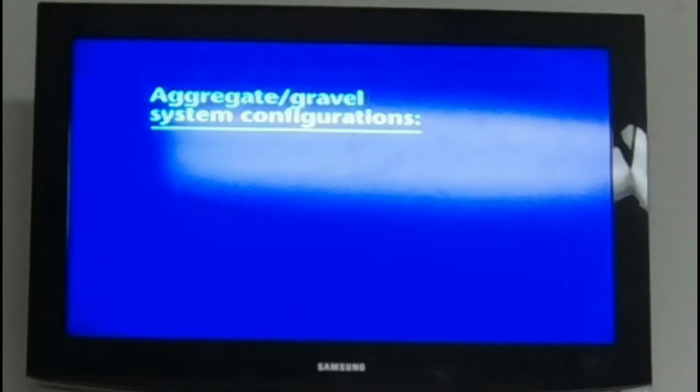On level or sloping topography of 5% or less, the level field method may be used. When this method is used, the absorption field shall be installed level with all absorption lines interconnected to form a continuous system. A standard T-fitting or approved distribution device shall be used to interconnect the absorption lines.